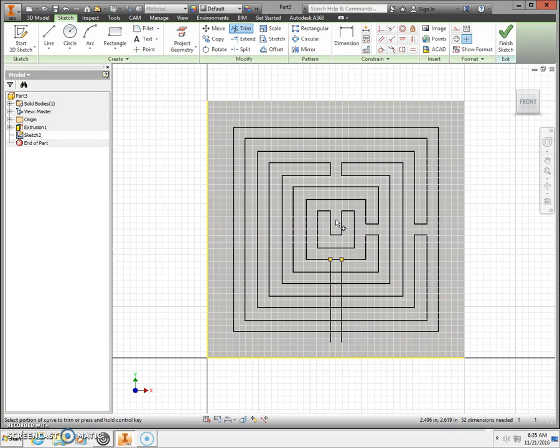So you can start beginning to follow this along with your cursor to get your BB out of the center groove. This one we're going to cut through. That's looking good. One more side to go. Start on the bottom, come out to the left hand side, make sure you get your green dot when you begin and your object snap when you're finished stretching it out. And we're going to trim.